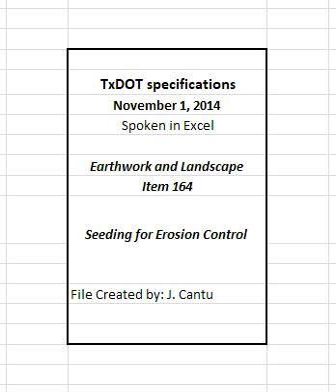3.1 Broadcast seeding. Distribute the seed or seed mixture uniformly over the areas shown on the plans using hand or mechanical distribution or hydro seeding on top of the soil unless otherwise directed. Apply the mixture to the area to be seeded within 30 minutes of placement of components in the equipment when seed and water are to be distributed as a slurry during hydro seeding. Roll the planted area with a light roller or other suitable equipment. Roll sloped areas along the contour of the slopes.